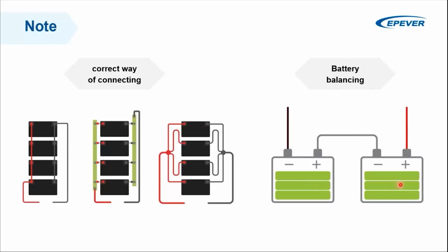You can disconnect the batteries when they are fully charged and check if they have the same voltages. If there is a voltage difference higher than, for example, 0.2 or 0.3 volts between them, this is a sort of problem, and you need to think about it and correct the way that they are being charged.